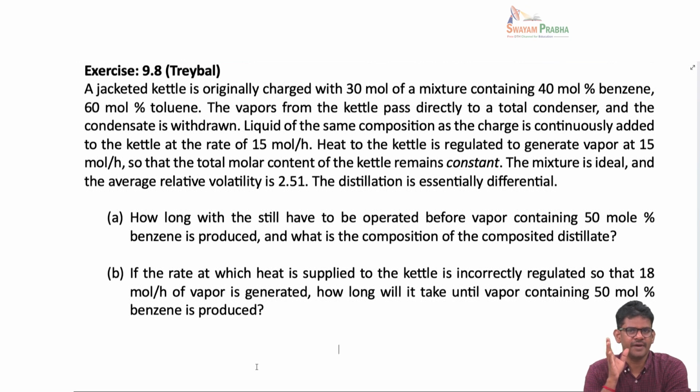So that means we need to find a way to see how the vapor that is coming out of the still is varying with time, and also keeping in account the new stream coming into this vessel. So what we actually need to do, we cannot directly use the Rayleigh's equation we derived before, which was for a batch system. Here now we are changing the operation completely. So we have to go to the basics. We have to go to the material balance problem.